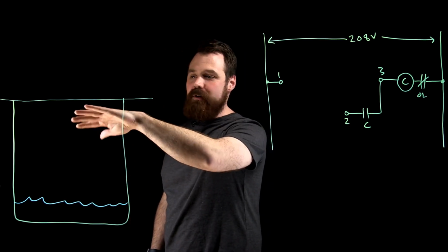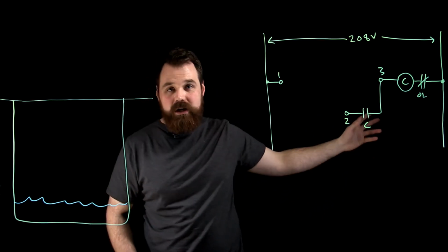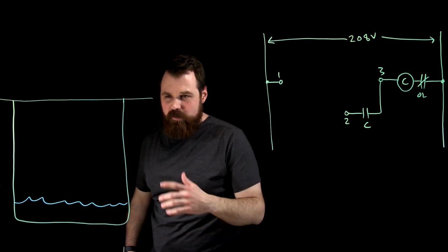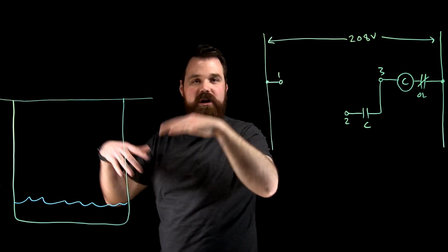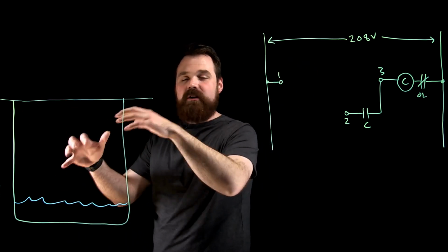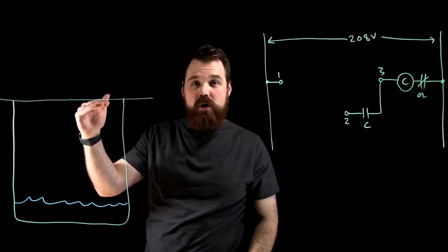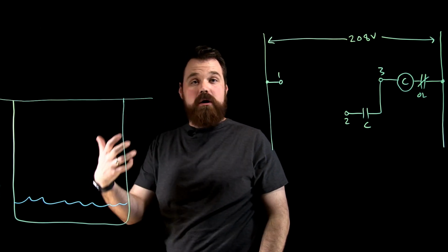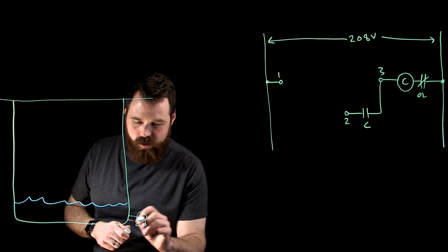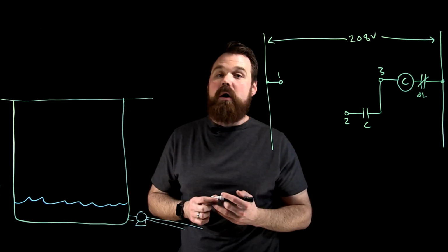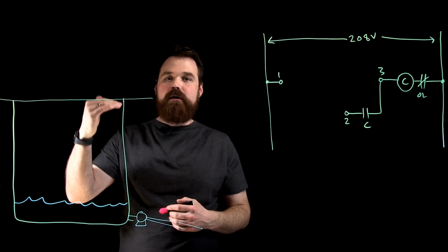When the water inside the sump pit reaches the top, it drains that pit out into the sewer system, right out into the drain, out into the river, wherever it goes. So think about this tank, right? All the water's rushing in from my parkade, snow's melting off cars, and the tank's going to start to fill. Once the water level reaches the top, or near the top, we want to start a pump. We'll have a little pump here, which will have a hose and feed that water out. So when our water reaches the top, that's when we want to start the system pumping.